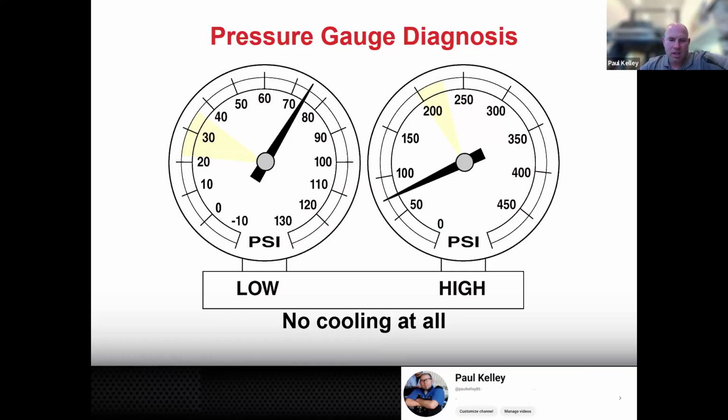Oh, I like that. I saw that come through the chat. Check to see if the AC clutch engages. And I look down there and you know what? Nothing. Nothing. So then what would you do? Well, for now, let's just say you're right. The AC compressor clutch, the compressor is inoperative.